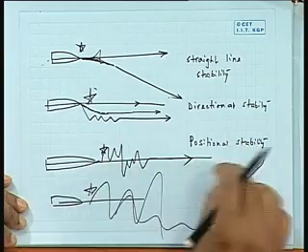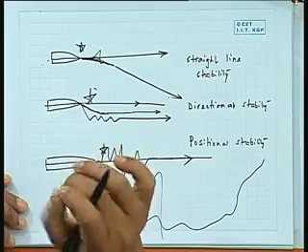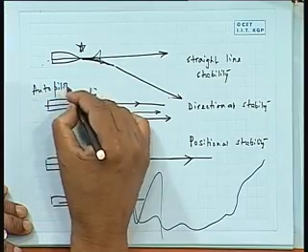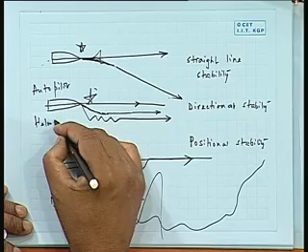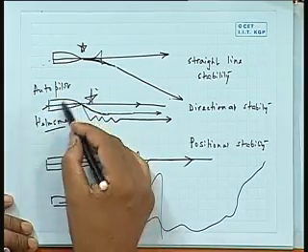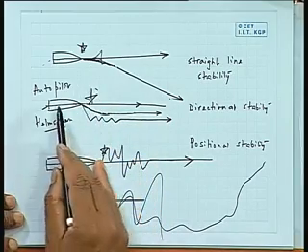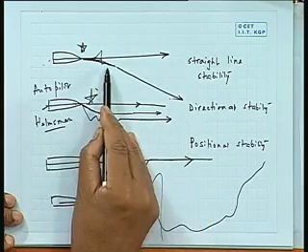The ship can have also position, it maintains the same line. Now, remember, a ship has no restraining force. So, if I have a ship going some place and you have given a disturbance, it has changed heading, nothing can bring it back if you have not made a correction. So, if you have an autopilot or a helmsman, or rather if you have no rudder, you cannot have this situation, because if you do not give a rudder correction action, you cannot maintain the heading, you can only have this stability.